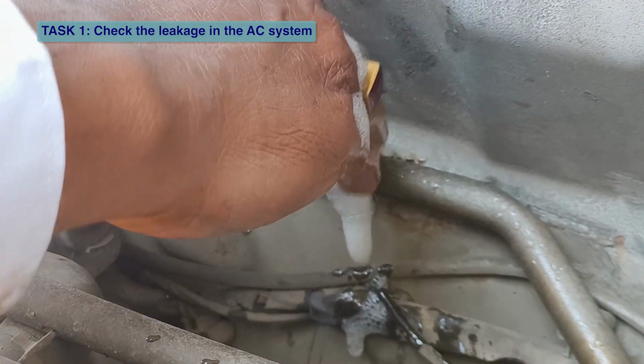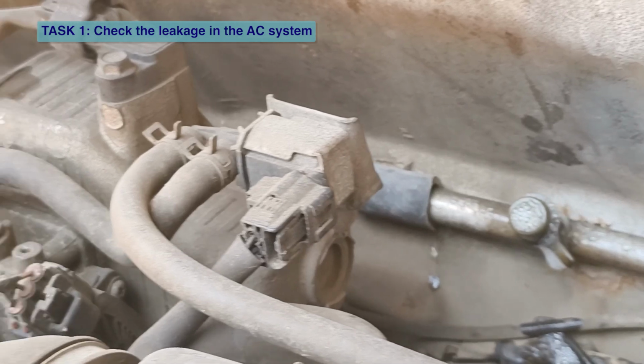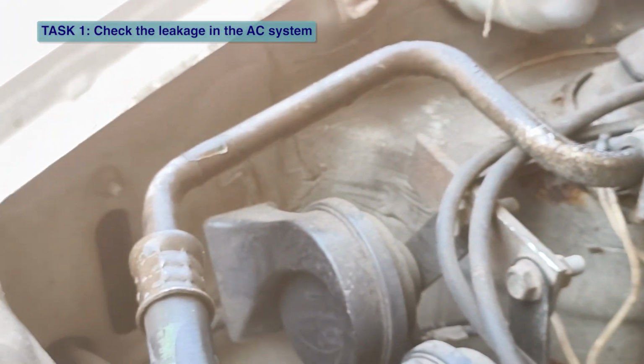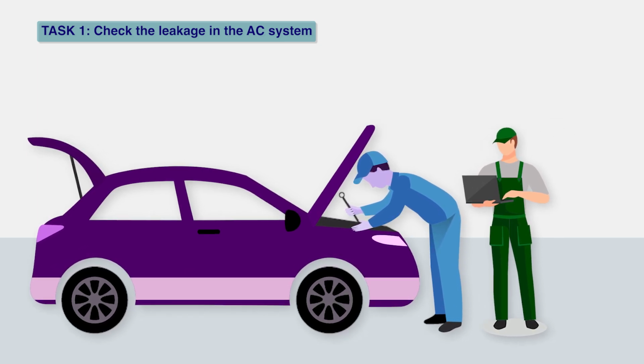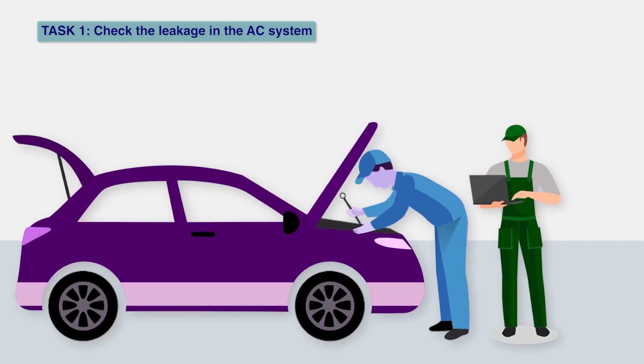Refrigerant leaks often carry oil with them, so look for oily residue near fittings, hoses or components. Document any leaks found, the location and the necessary repair to ensure proper sealing and functionality of the system.